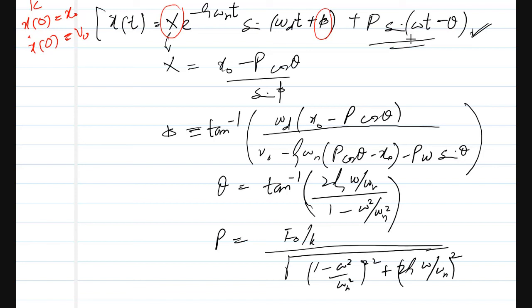In this lecture we have talked about how to model forced vibration. We have seen which factors are important in determining the amplitude of the forced vibration, and we have seen the graphs of how the amplitude varies and which factor we have to control. Finally we have seen one application, that is rotation unbalance. In many real applications the center of mass does not align with the center of rotation, so unbalance occurs, and that unbalance creates forced vibrations. You can analyze these forced vibrations, and to eliminate them we have to balance the body, otherwise the vibration will take place continuously.